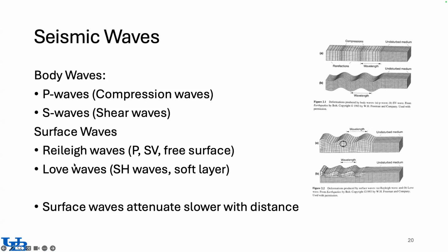and that motion is also reducing as a function of depth, so they are more noticeable near the surface. And we have Love waves, which are caused by the interaction of SH waves, when we have a sedimentary layer, a very soft layer above a stiffer layer, where SH waves are trapped and move between the top and the bottom, creating a sense of motion that is transverse to the direction of propagation, but the amplitude is decreasing also with depth.